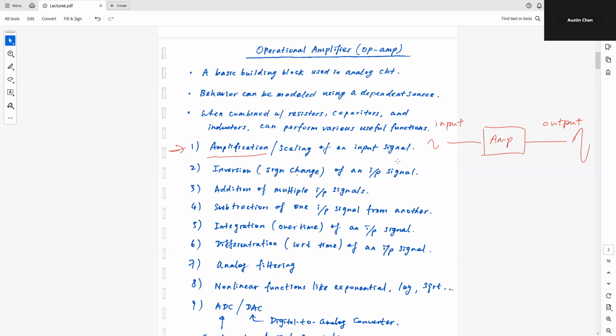What I can also do is have this op-amp perform inversion. The inversion allows you to present a negative sign to what you put in, and you will see that sign inversion at the output. For example, if I put in, again, a small sinusoid, but this time I have the input inverted, then after going through this amplifier, I expect to see the same sinusoid. I'll redraw it over here. It's a gained up version of what I put in, but now the signal is inverted.